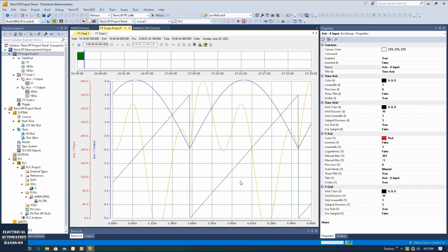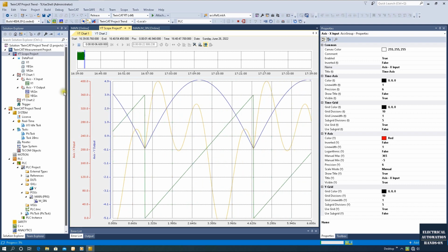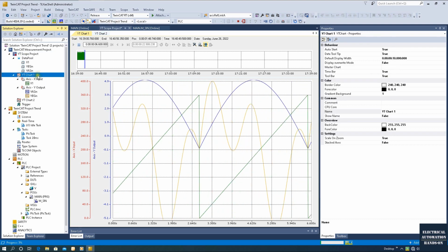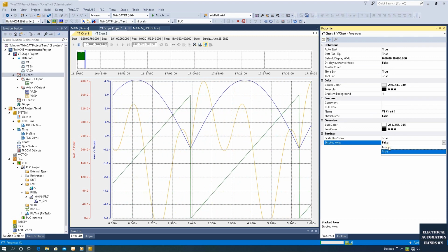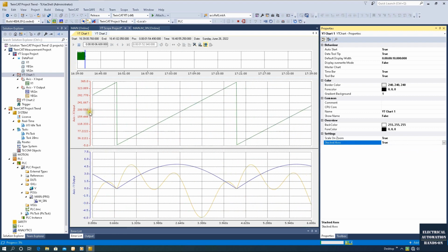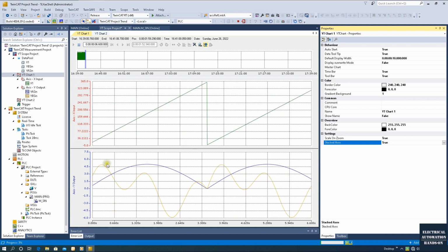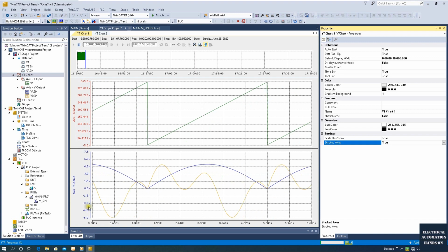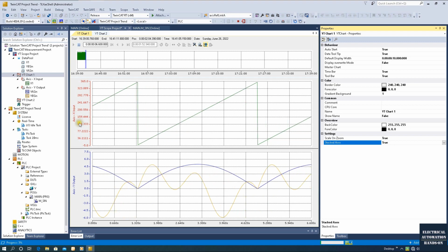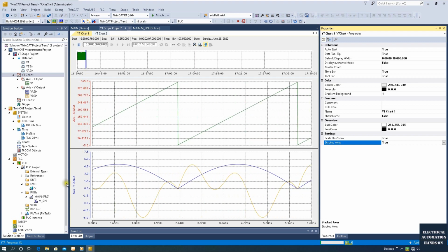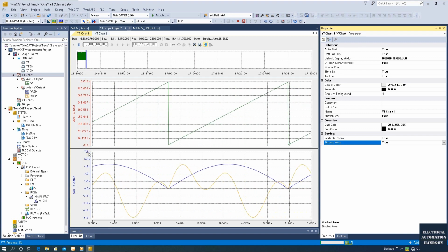In some cases, showing all those values in one chart looks a little bit messy. Then you can click this chart 1 and select this stack axis. Once I switch it to true, it will separate. So this is the input, this is the output. This is very clear. In some cases, this area can record all the motors' torque values, and this can record all the motors' current or speed values. This is the speed value, and they use the same axis. The torque values also use the same axis, because the units are the same.